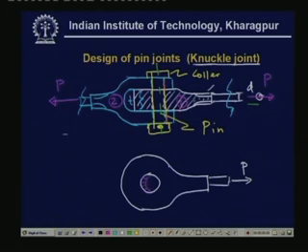So the material may also tear away, that is this part, if the load is too high, then this can come over here. So it can just tear away. So when it tears away, then of course this is one such critical section, it just goes away. Normally it should not go straight, it may go in a radial way also. But we can design roughly based on this mode of failure.